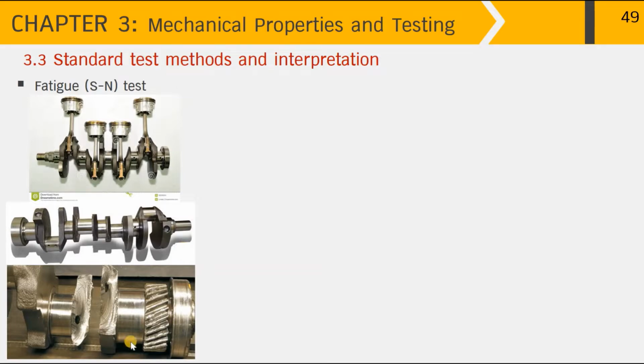However, during service under fatigue loading, unfortunately, it failed, showing the fractured surfaces like this, as you can see in this picture. For fatigue failure, it is typical that you can see a very unique characteristic on the surface. It's very unique that you can find the beach mark on the fatigue surface like this. And by looking at this beach mark, it will finally lead to the initiation of the fatigue crack, which we can see as the big porosity here.